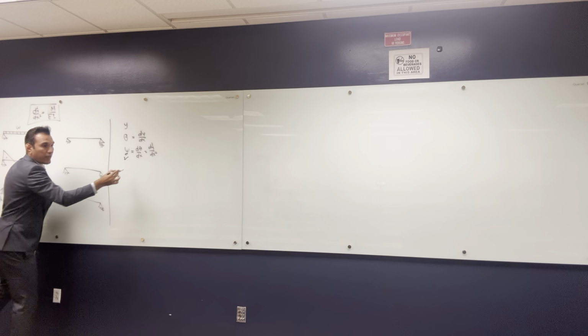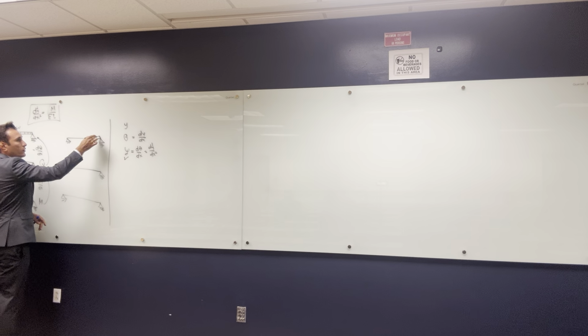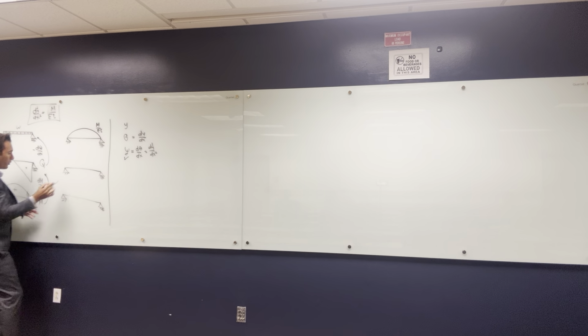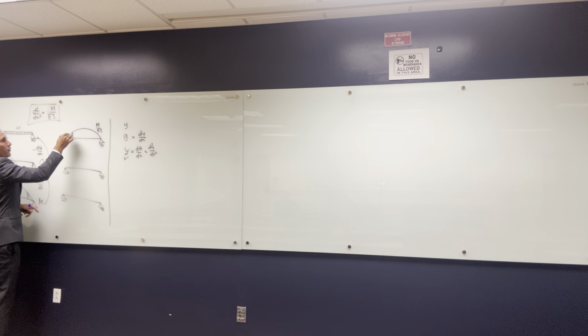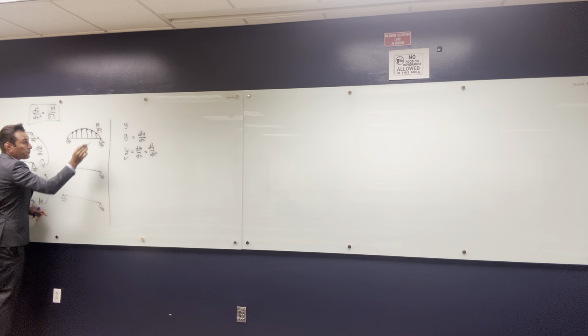It's very direct. You have the moment diagram, so basically this is M. Basically you divide M over EI, you can get the curvature at any location of the beam. That is the easiest quantity that I can get. So to get theta and y, it's a little bit more difficult. Why? What you are going to do is take M and put it as a load on the beam, and then divide M over EI, and if it's positive, you are going to put it as a load going up, because that is the positive direction.